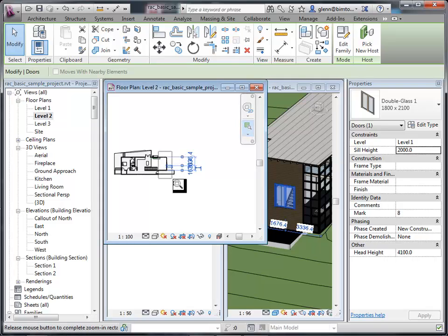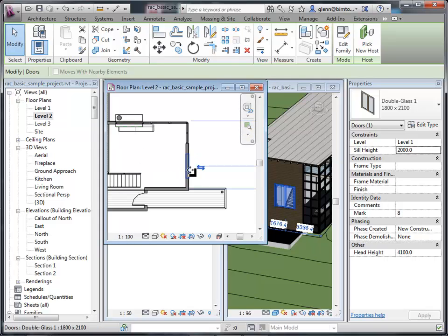Let's zoom on in and see. That's interesting. I see it's almost the ghost of it because I can see that little change thing. It doesn't think that it's actually there. Oh, you know what it is? It's because although it's poking up into level 2, its top isn't quite at 4 feet above level 2 just yet. So let me try shoving that up just a little bit higher.